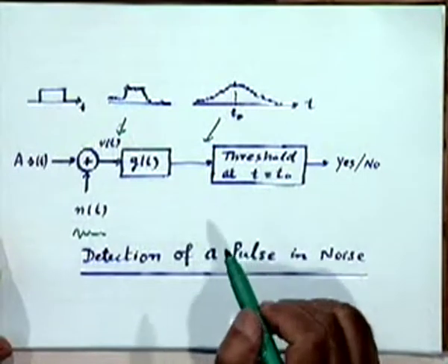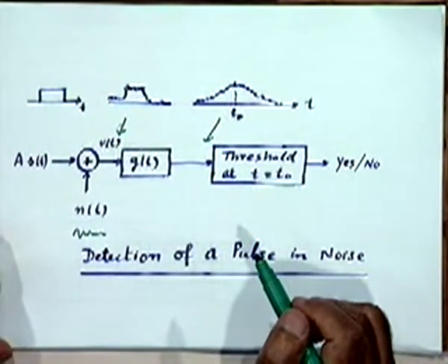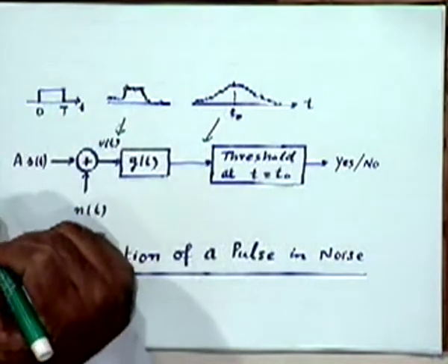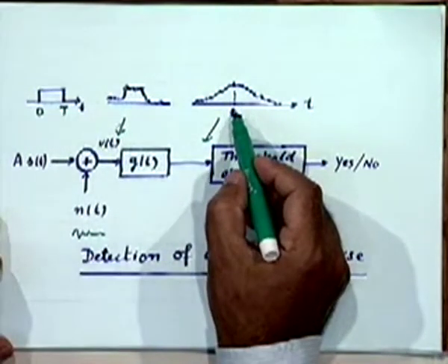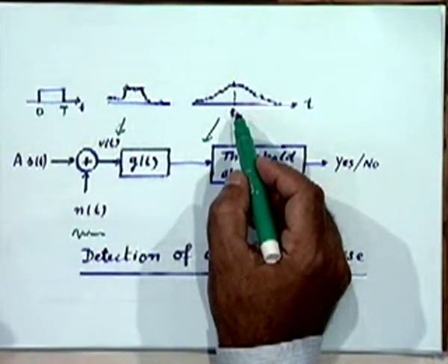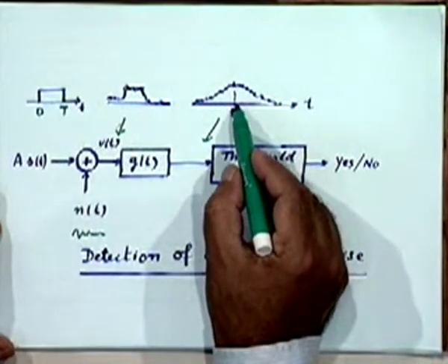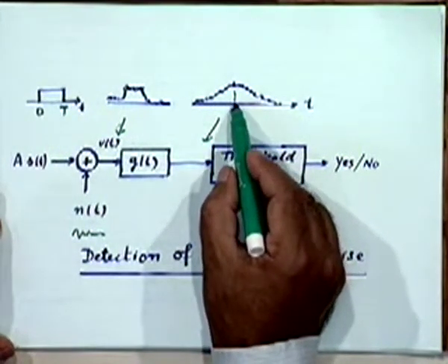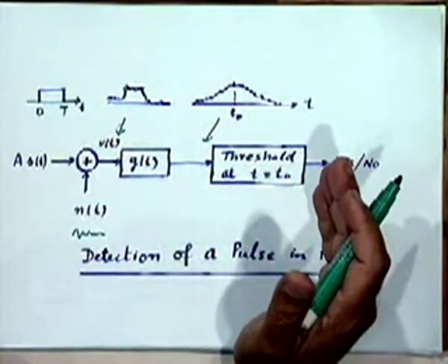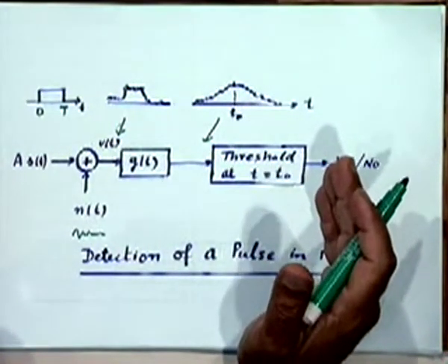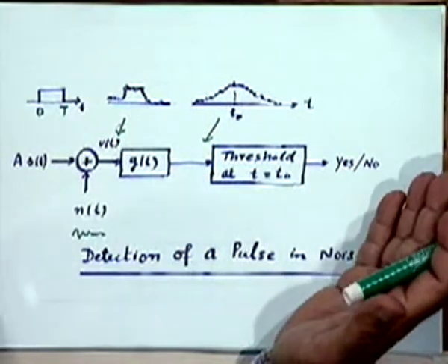So the point at which we sample shall depend upon the nature of the signal and the pulse shape. I'll tell you what that point typically will be. Suppose this pulse is of duration T, right? Typically this point t0, intuitively you should know it should be at a point by which you could have seen most of the signal. In fact, you should have observed most of the signal, in fact all of the signal.